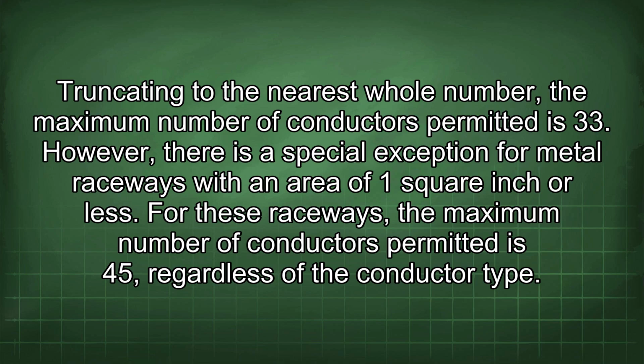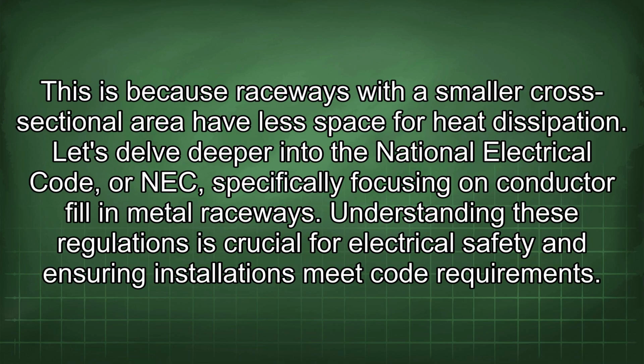However, there is a special exception for metal raceways with an area of 1 square inch or less. For these raceways, the maximum number of conductors permitted is 45, regardless of the conductor type. This is because raceways with a smaller cross-sectional area have less space for heat dissipation.